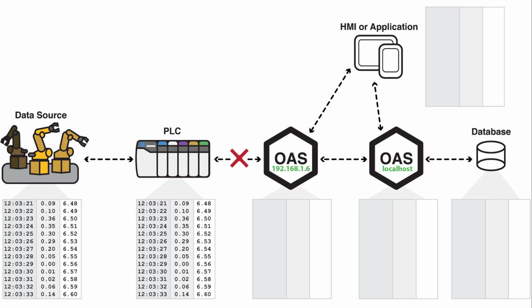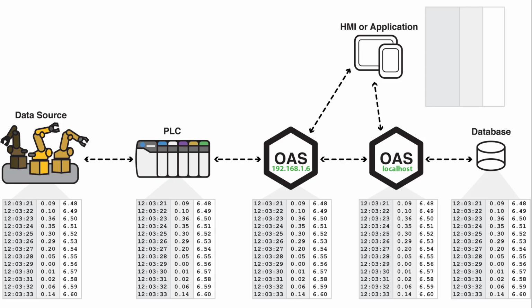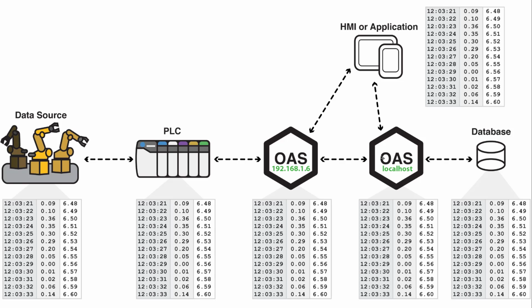Built into the communication drivers is redundancy for communication failure, so you can have a second parallel path as well. As that problem is resolved, it would be able to collect the data from the controller and then pass it on to the user interface and the other data logging engine itself.